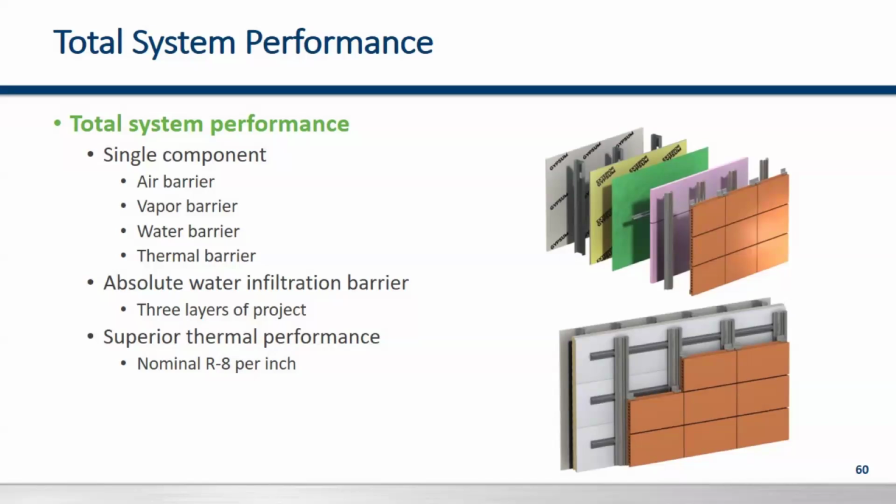I want to highlight down on the lower right-hand corner, this is terracotta, but this could apply to a plate system. You can see with the panel orientation and the type of Rainscreen that's being used on the exterior, some additional subframing is required, and you can see that. A lot of the subframing would typically be a light 18 gauge galvanized hat channel.